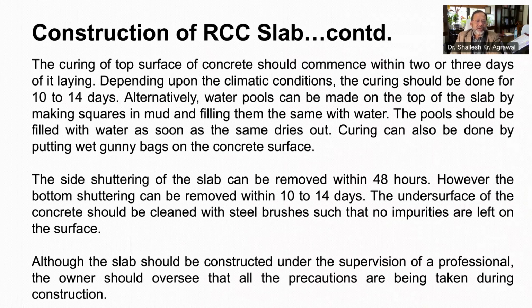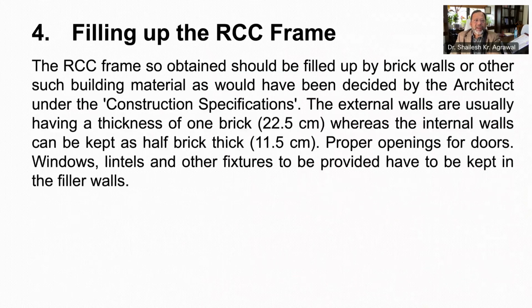The side shuttering of slab can be removed within 2 days. However, the bottom shuttering can only be removed within 10 to 14 days. The undersurface of concrete should be cleaned with steel brushes so that no impurity is left.